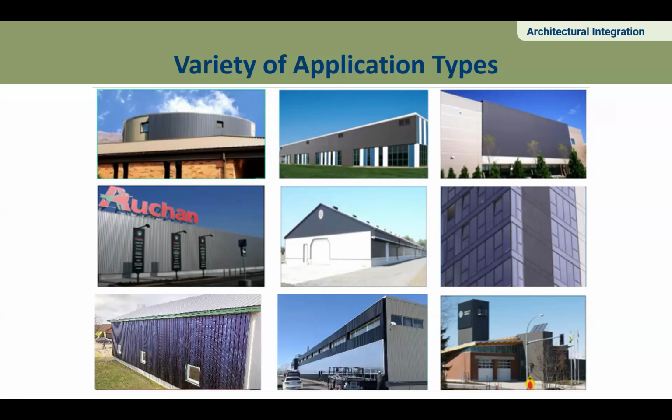And then also fire departments really like it. In the lower left-hand corner, that is a fire department that has a fairly sustainable design. You can see some of the solar PVs on that, but that tower sticking up is clad in the transpired solar collector, bringing in warm air directly into the hose dry tower. So they coil up their hoses and then drape them through that tower to let them dry out. That warmer, drier air, they found, extends the life of those hoses by 5 to 10 years because it helps prevent the dry rot through conventional heating. So another benefit there as well.